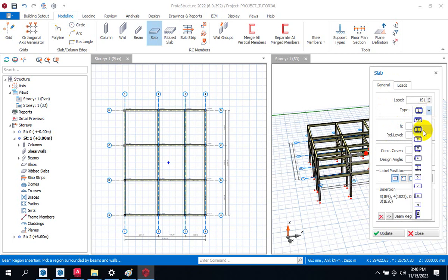Type 1 means this panel is an internal panel. You see it shaded top, bottom, left, right. Type 2 is telling you that this panel is continuous in 3 different ways, but discontinuous in 1 way. Ranging by eye, you can see that the long side is a rectangle. A rectangle has 2 long sides, 2 short sides. So one of the long sides is discontinuous, while the 3 other sides are continuous.